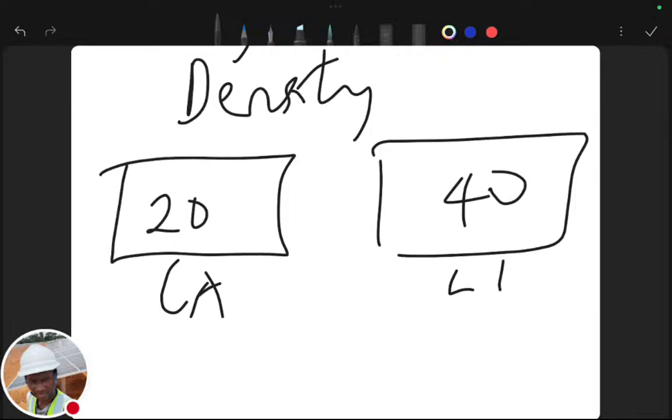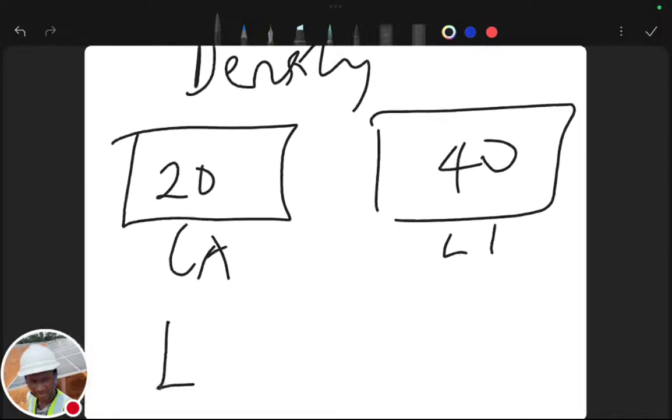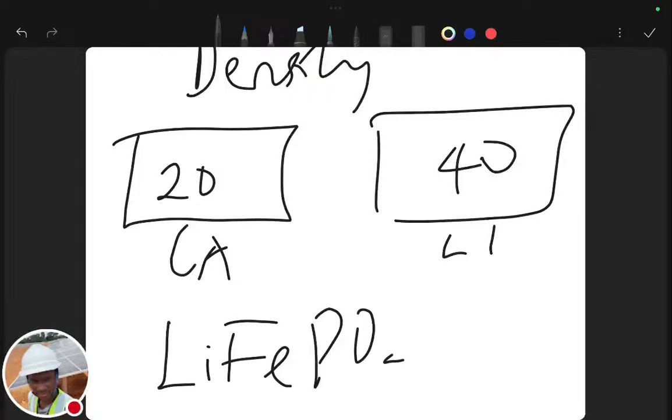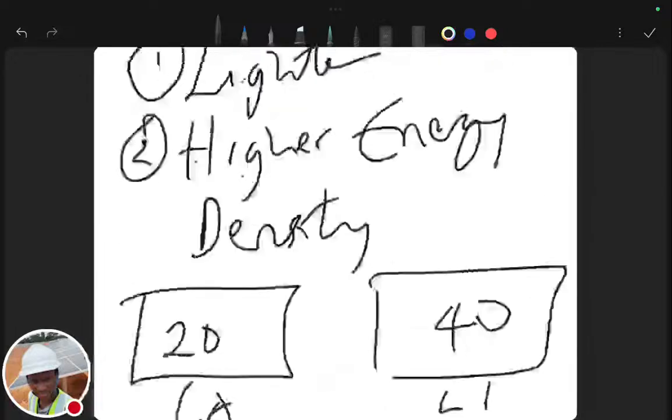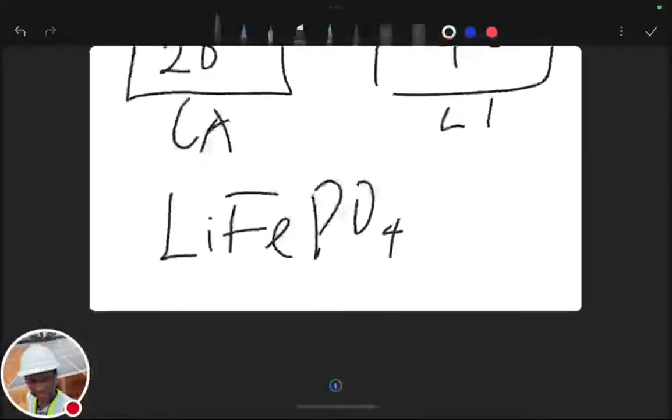So lithium-ion batteries are actually preferred. When I say lithium-ion, the best type of lithium, we don't usually use the real lithium-ion. The real lithium-ion has a lot of problems. What we usually use is the lithium-ion polymer and LiFePO4. This is better, it is smaller, and it's a lot less dangerous. It is safe. So assignment number 3, I want you to list the different types of lithium batteries and differentiate them. That is the third assignment.